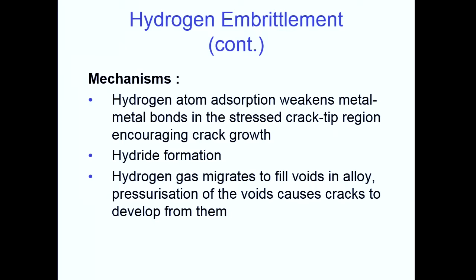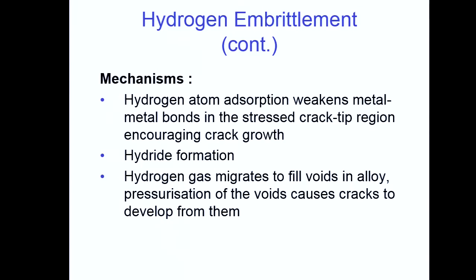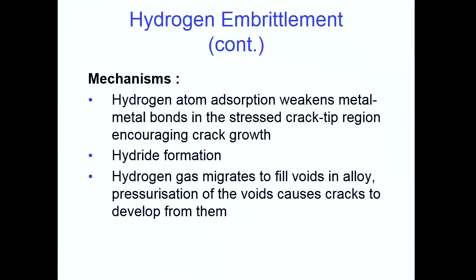I'm also struggling a little bit with why there are a load of voids being formed. If you've actually got to the point where the stress is high enough to cause voidage, it's probably high enough to cause mechanical cracking, and then you don't need any hydrogen. So it becomes almost like a fracture toughness problem. So I've put all the mechanisms there. People are still working on it. That's the bottom line. We don't really know.